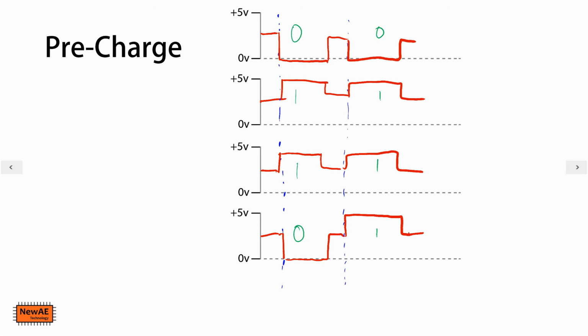Now, the really interesting thing as an attacker using this information is that if we look at the power, once again on the positive rail, at this clock cycle here, you'll notice there are 2 transitions that go from that pre-charge state to high. So this means it's going to charge 2 of these effective bus line capacitances, so we'll see a spike that's 2 units large.